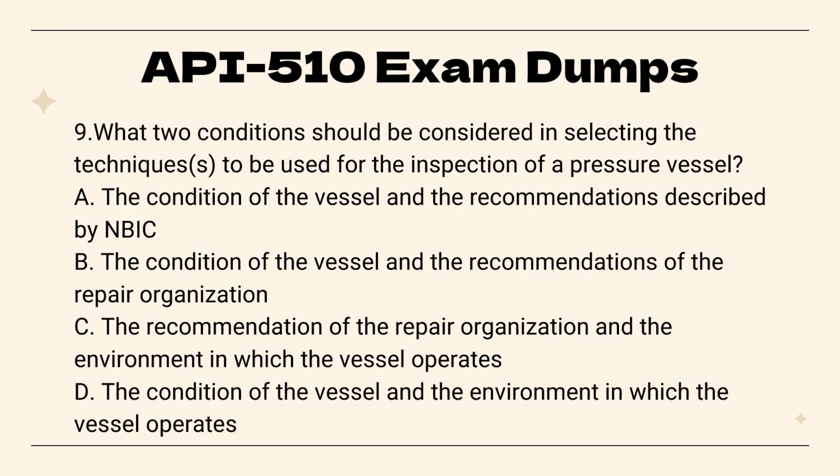9. What two conditions should be considered in selecting the techniques to be used for the inspection of a pressure vessel? A. The condition of the vessel and the recommendations described by NBIC. B. The condition of the vessel and the recommendations of the repair organization. C. The recommendation of the repair organization and the environment in which the vessel operates. D. The condition of the vessel and the environment in which the vessel operates.